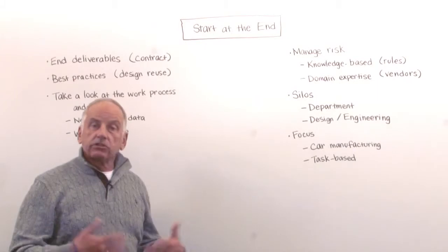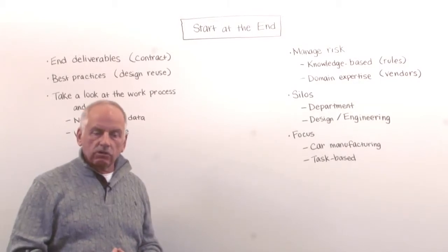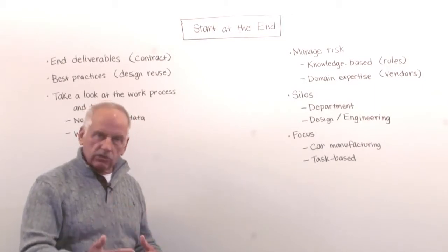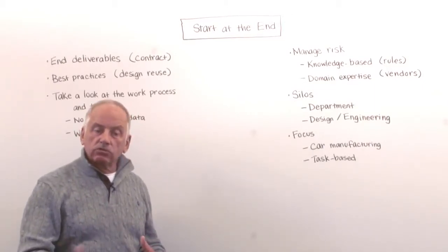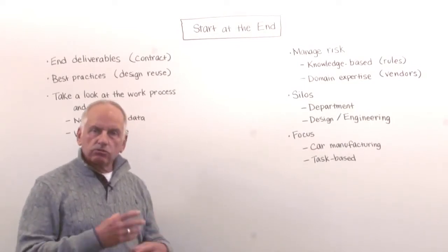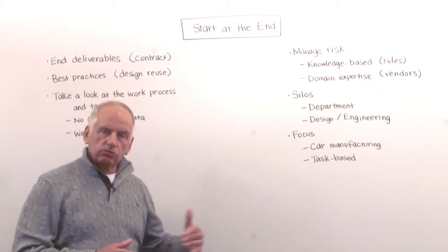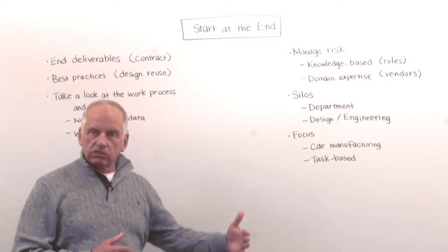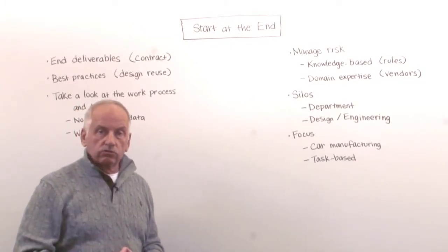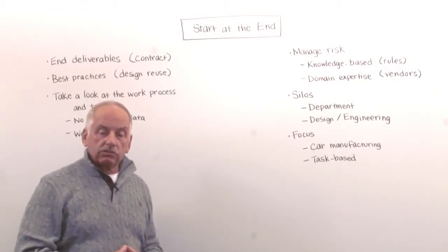So if you have a project, for instance for Shell, which is a good example, but other owners like Aramco and so on have the same thing. They have what they call the DEP, the design engineering practice, and Aramco also has something similar, and I'm sure that ExxonMobil and other owners have the same thing. Now, it would be good if you can capture those key design parameters and rules upfront and put them into a rule system. So when you do the design on your P&ID or any instrumentation or in 3D, it doesn't really matter, you can run those rules while you do the design, or do them at certain stages of the design, to make sure that you're doing the right thing early on.